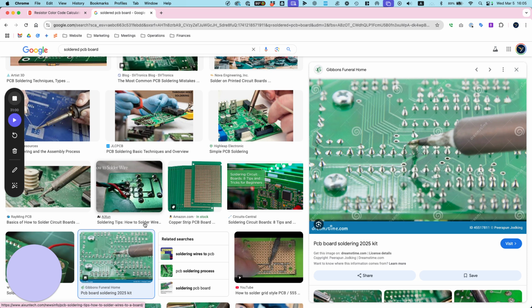I'm not going to talk about this plug just yet. This is called a balance plug. As you know, we have multiple cells inside. When you're charging, you want to make sure they're all at the same voltage, more or less. That's what this plug allows you to do. This is our usage plug right here, the main plug. This allows me to take the entire voltage out of this battery, and this is what you plug into your drone.